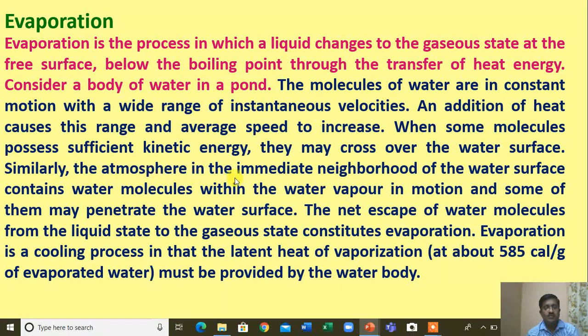Similarly, the atmosphere in the immediate neighborhood of the water surface contains molecules of water vapor in motion, and some of them may penetrate the water surface. The net escape of water molecules from the liquid state to the gaseous state constitutes evaporation. Evaporation is a cooling process in that the latent heat of vaporization, about 585 calories per gram of evaporated water, must be provided by the water body.